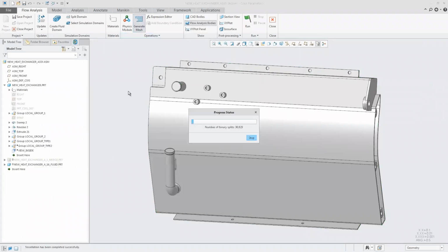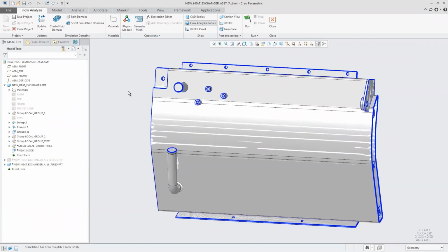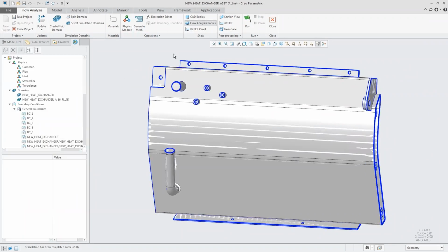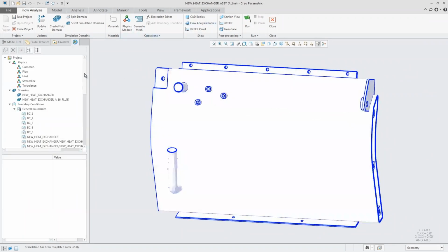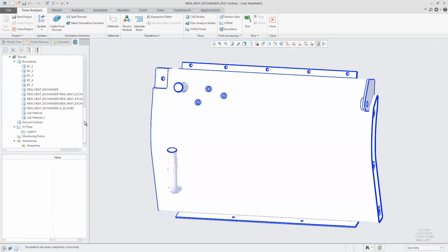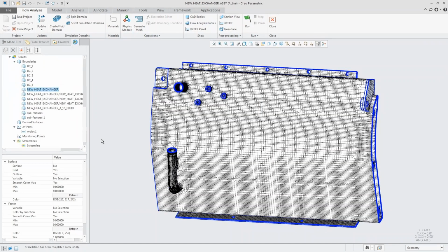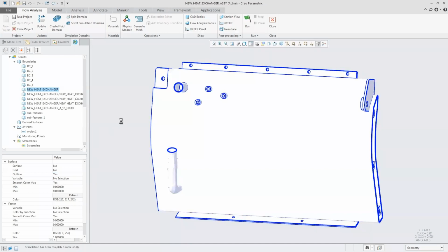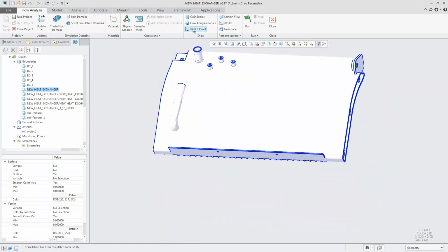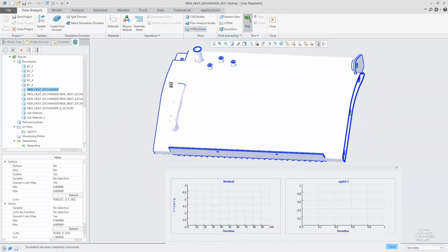And once we have that all added in, we can define the mesh for our fluid flow analysis. Again, Creo actually builds out the mesh for our model automatically. We can just simply open that up and check that out. Make sure that everything looks good here for our mesh. We can take a look at that, review it, make sure that we like it. If we wanted to go through and make any changes, we could do that. But in my case, I'm happy.